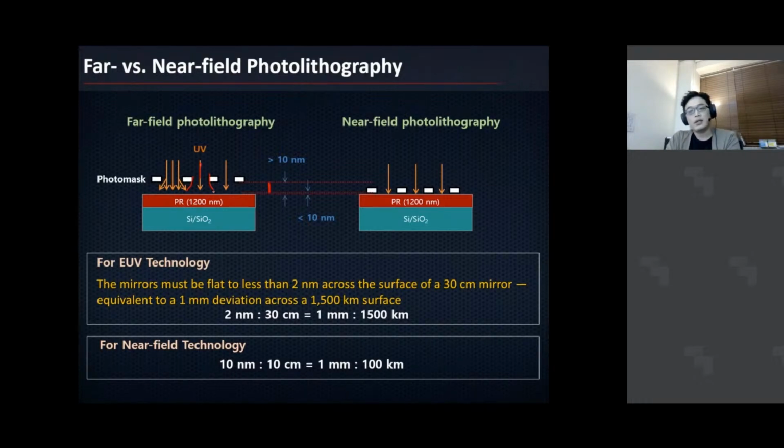So what it means is, if you are a student or postdoc and go into the clean room right now and do photolithography, using the typical Shipley 1805 photoresist, and you get a 2 micrometer electrode feature, you are very successful. That's not because your photomask is small enough. That's because you always have a diffraction issue.